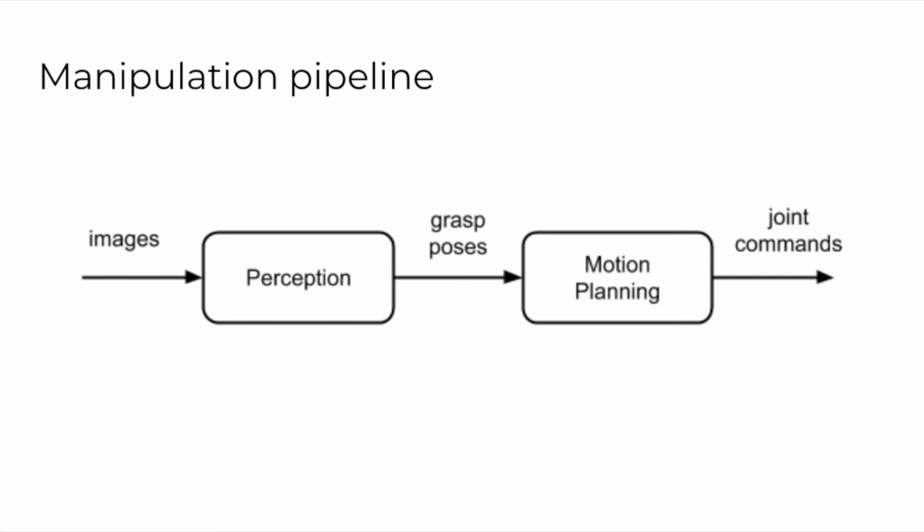The manipulation pipeline is shown on the slide. The captured image from the camera is fed into the perception system with some pre-processing, and the grasp poses needed for each of the cans are calculated. Then, with a nominal trajectory, the inverse kinematics is solved and optimized in Drake using a mathematical program, and out go the joint commands to actuate the IIWA.